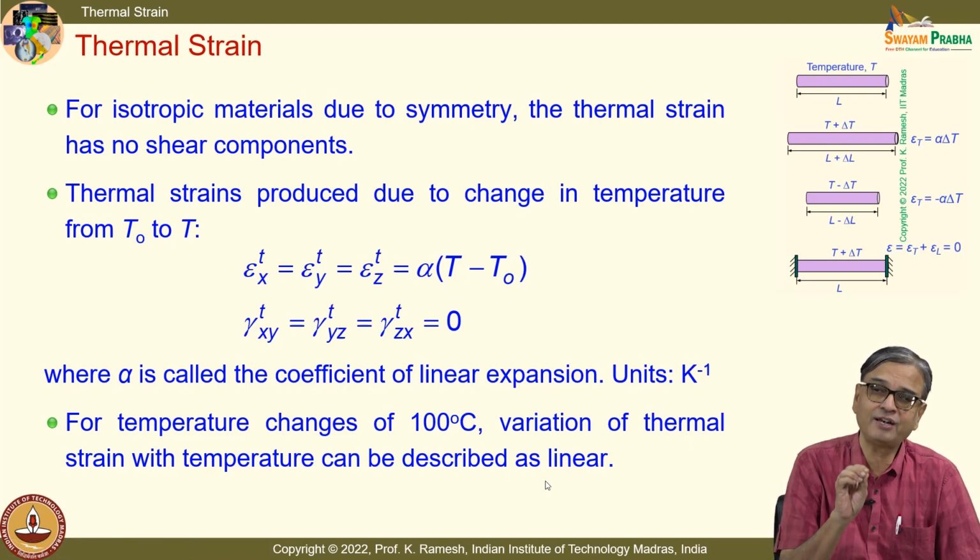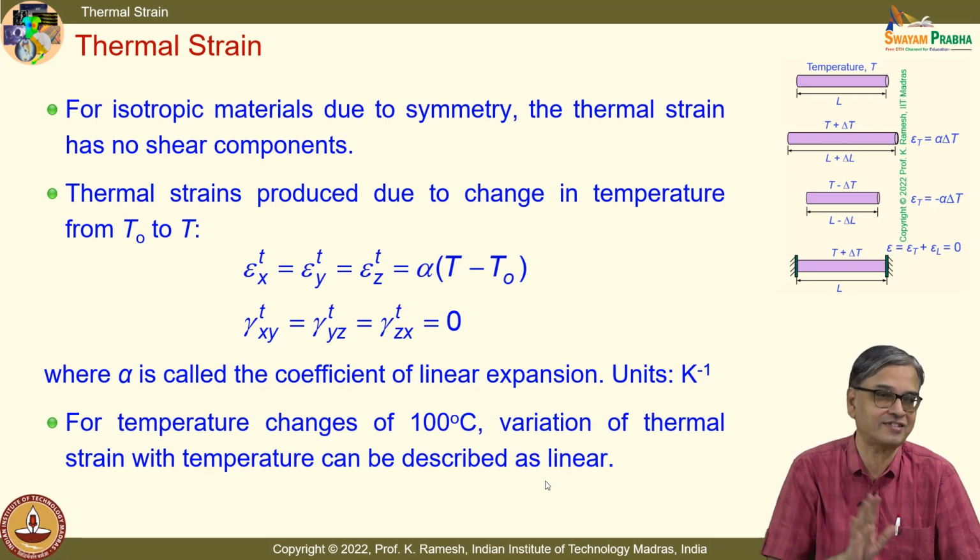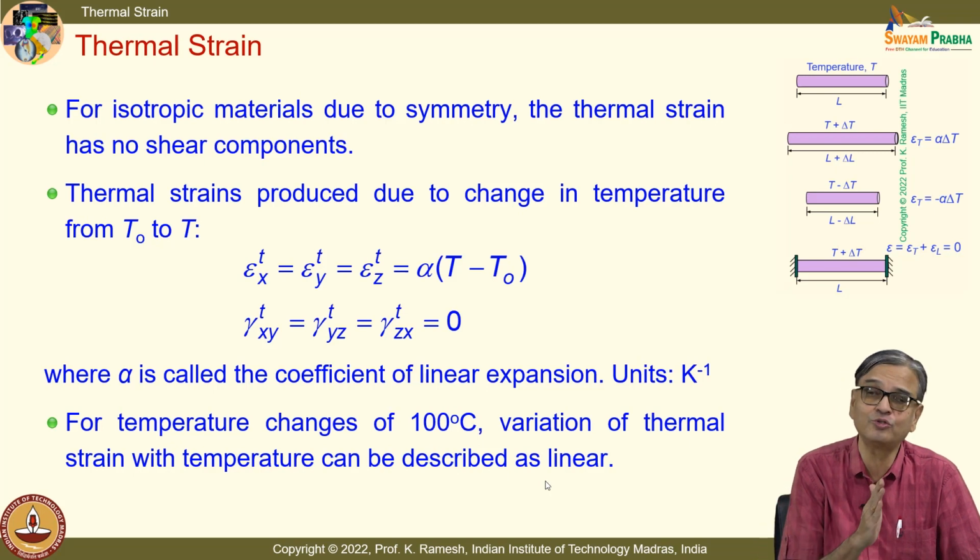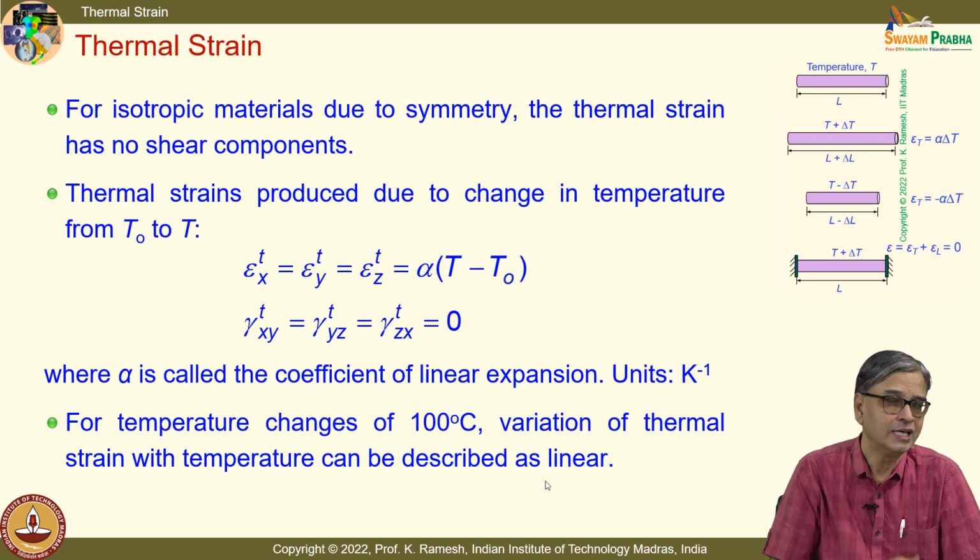See, we would like to work in linearized elasticity because that helps you to simplify the problem, split a complex problem into an assembly of small problems that can be individually solved, and the stress tensor can be added, provided you have the same reference axis.